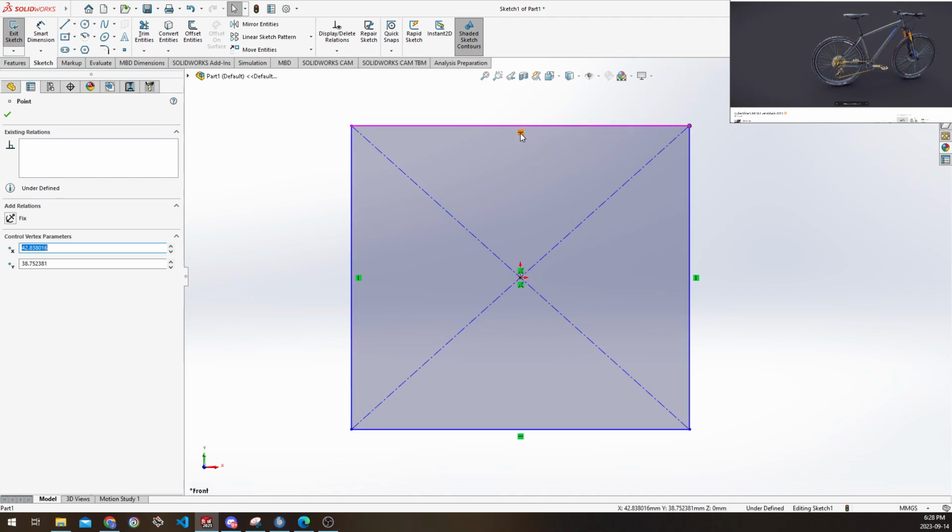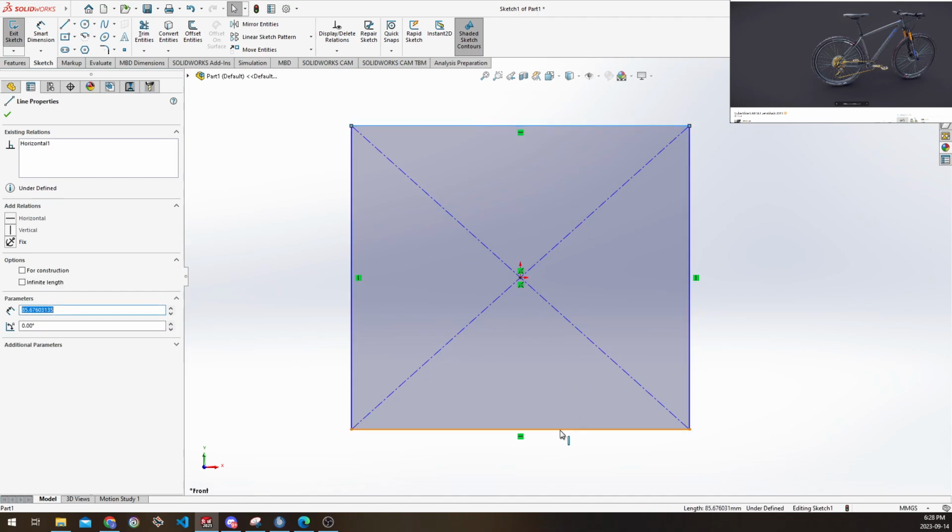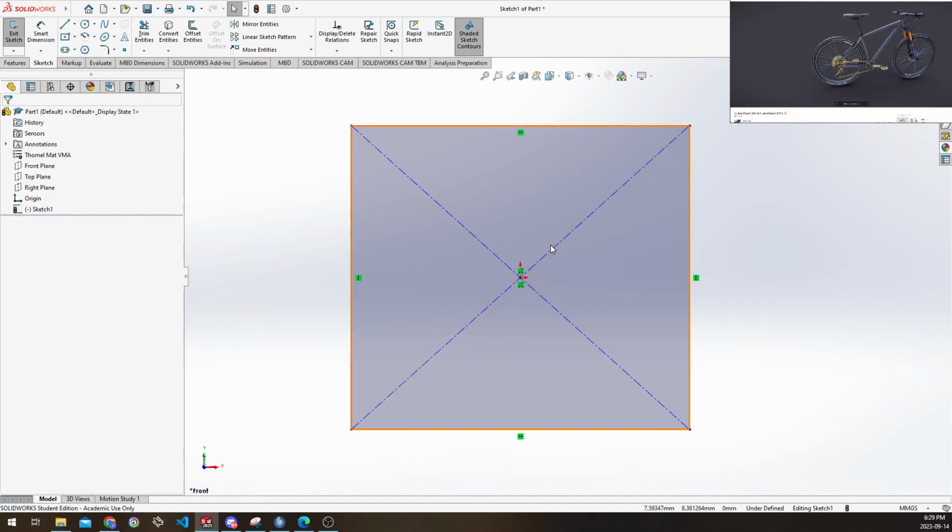For example, it'll automatically make the top and bottom parallel, the left and right parallel, and then it'll add these cross lines from the corners, which are equal to each other, which means that the corners will be 90-degree angles. So these shortcuts up here will always be fully defined when you put them in. You don't have to worry about your corners being off by a little bit. Whenever you use these tools, the definitions will be correct. The only thing is the scale will not yet be set. That's what I'll talk about next.